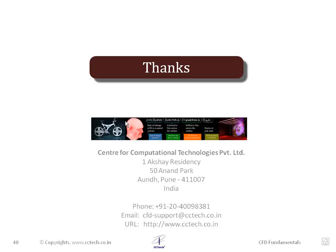So I hope you could follow the lecture today about the finite volume method, how we are able to obtain from the partial differential equations a set of linear algebraic equations, and we combine all the linear algebraic equations and try to obtain a solution for a given transport property phi, and this can be done for all the governing equations. I hope this lecture was helpful for you to get a bit more insight into the numerical scheme which is applied in commercial software packages like Fluent, CFX, or any other software which is available in the market.